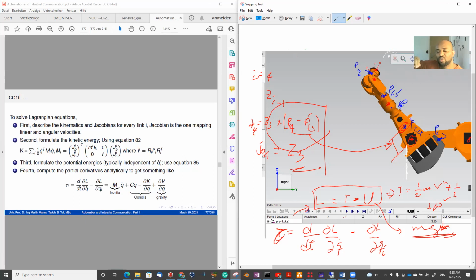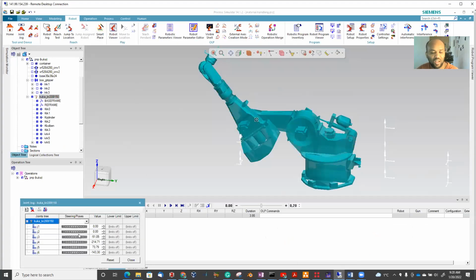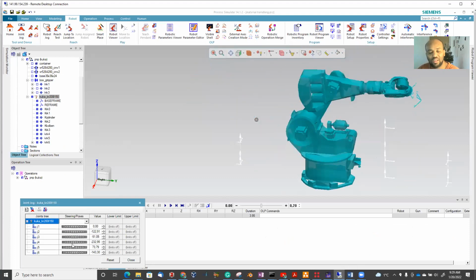You would like to control the robot precisely at some specific position. In order to do that, there is inertia of the robot which affects the performance of the motor. So you have to know how to compensate these dynamic behaviors by including a dynamic model in your kinematics. Otherwise, a simple jogging operation doesn't solve industrial problems. This is just kinematics. Nothing else is here. It's only forward and inverse kinematics behind this software.